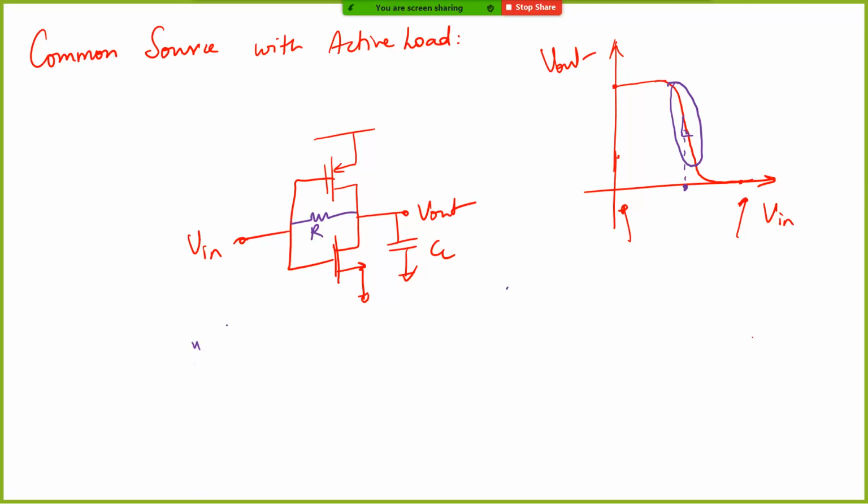So this with the resistor is called a self-biased inverter, and in fact, this is used fairly well in a lot of situations, especially when you have high-speed links. An example of high-speed links can be your DDR interface, your DDR RAM with your processor. You want the data rate to be pretty high, right?